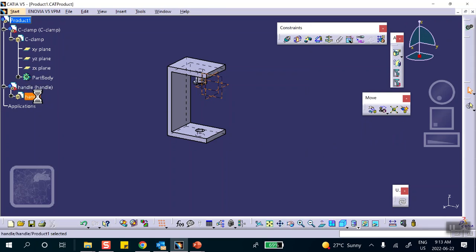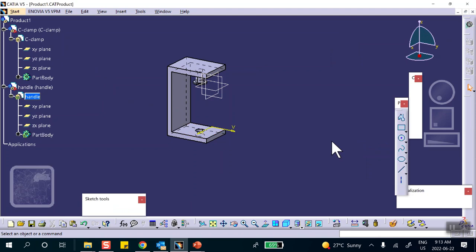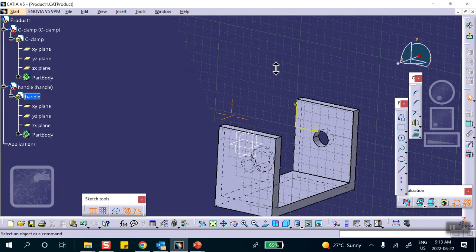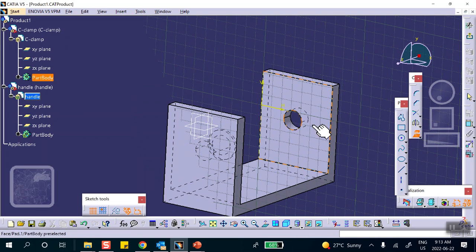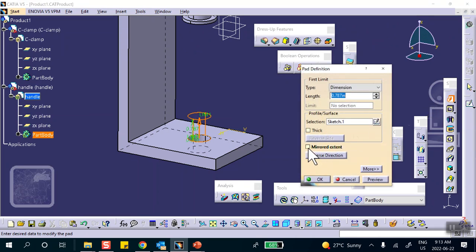All right, let's go make it. Double click on this plane. I will sketch. Why don't I project the circle, which is going to get inserted. This handle is going to get inserted into this thing, and notice it got projected. So up, out. I mean, and pad it. Why don't I do this thing in both directions? Really doesn't matter, but okay, good.